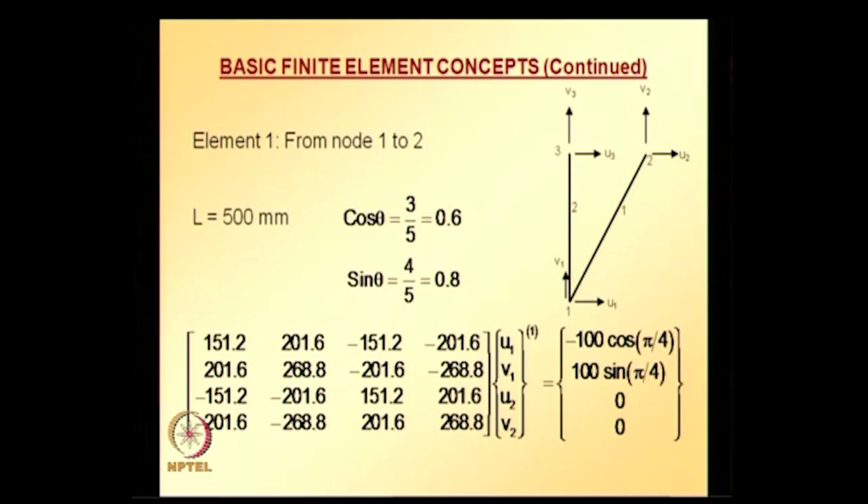And here if you see the element equations, load is applied at node 1, and the loads applied at a node can be arbitrarily assigned to any of the elements, that is you can assign those loads to element 1 or element 2, but here it is assigned to element 1. Alternatively the nodal loads can be assigned to the global load vector directly.